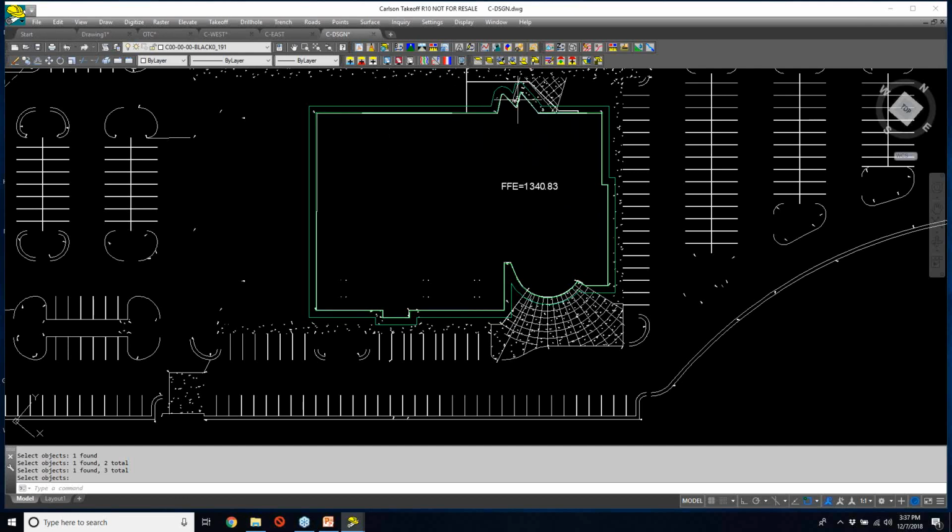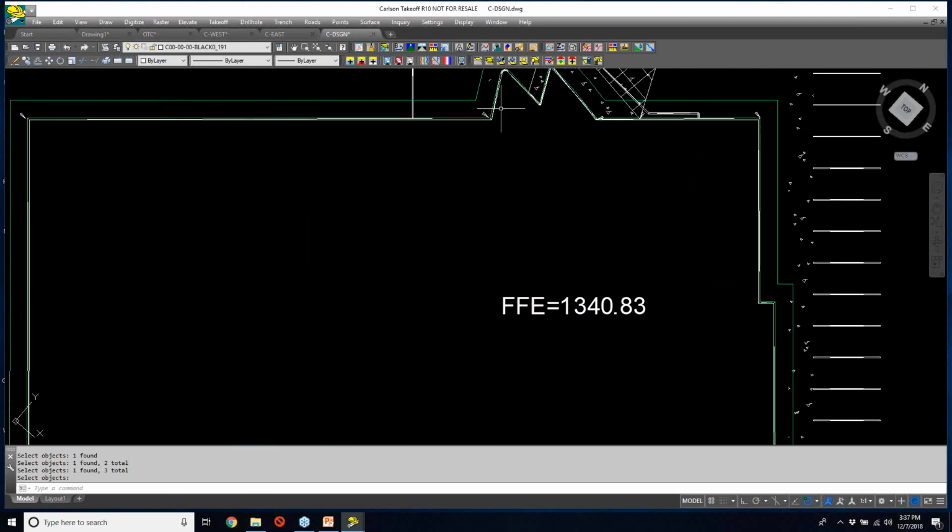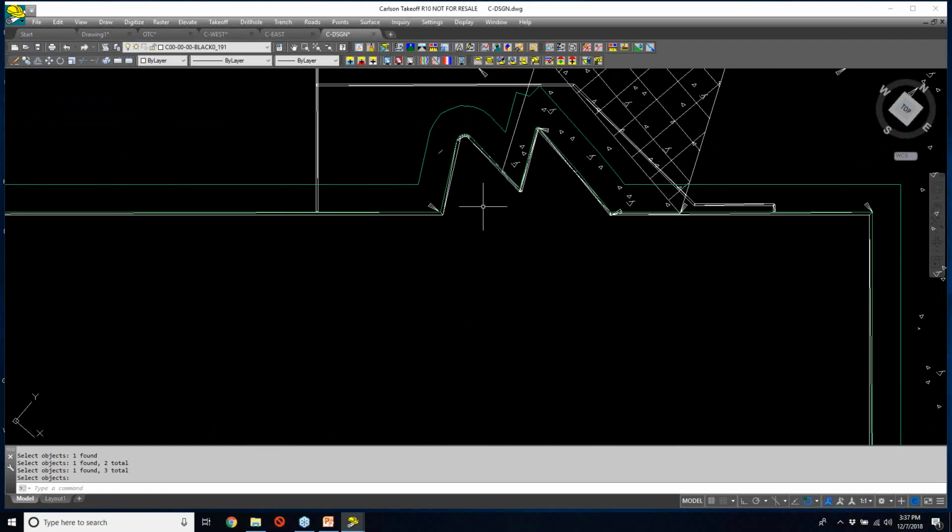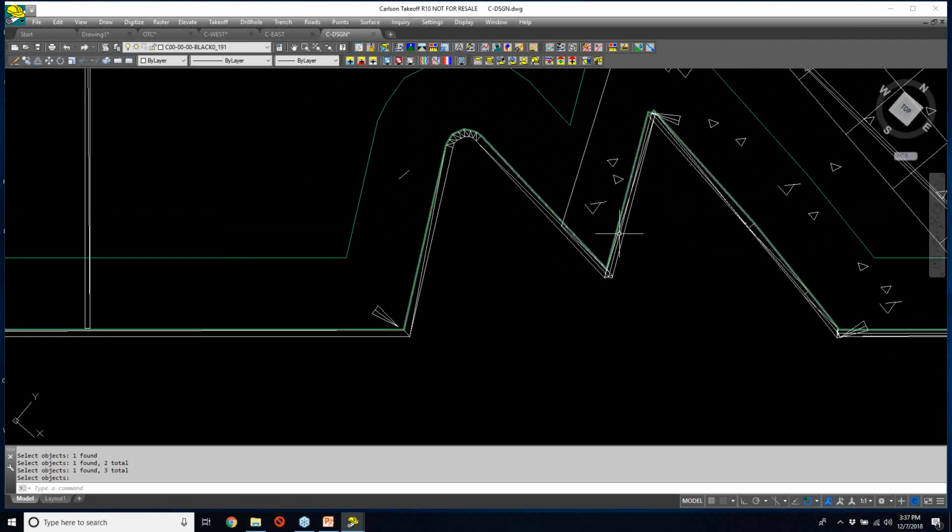But that was a very interestingly shaped building, and I didn't want to have to redraw it all by hand. So to draw this building outline, we use the shrink wrap entities command. But because there are entities already on the layer of these other triangles that were determining the building walls, I had to create small selection sets of the triangles in here, being careful not to select other triangles and the hatch stipple patterns.